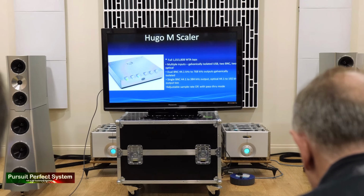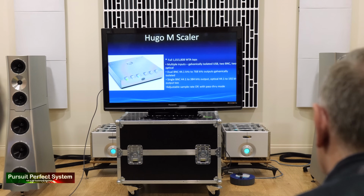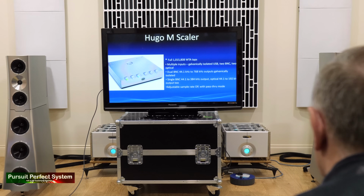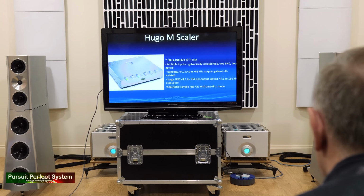Hugo M scaler. This has the full 1 million taps, and it's got multiple inputs, galvanically isolated USB, 2 BNC inputs and 2 opticals. Dual BNC outputs, single BNC outputs for feeding with other DACs, and an optical output. That was there for when you want to do your own recordings to convert 44.1 into 176.4. And it's got adjustable sample rate outputs, and it's got a pass-through mode, so you can easily hear the difference of the M scaler being switched in and out.